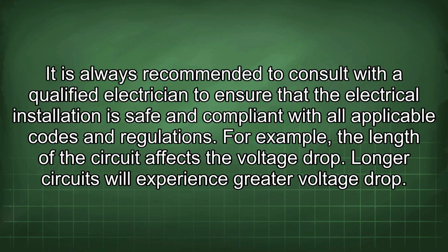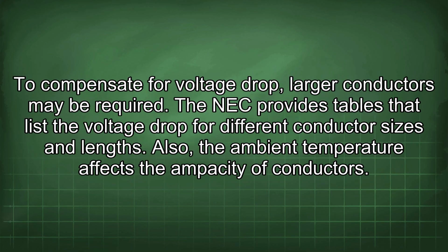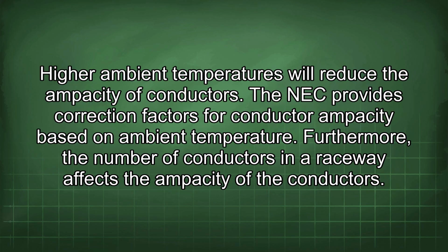For example, the length of the circuit affects the voltage drop. Longer circuits will experience greater voltage drop. To compensate for voltage drop, larger conductors may be required. The NEC provides tables that list the voltage drop for different conductor sizes and lengths. Also, the ambient temperature affects the ampacity of conductors. Higher ambient temperatures will reduce the ampacity of conductors. The NEC provides correction factors for conductor ampacity based on ambient temperature.